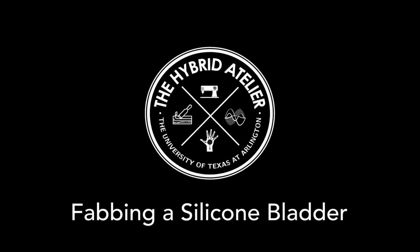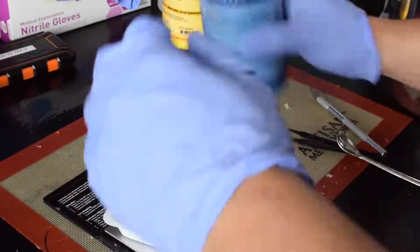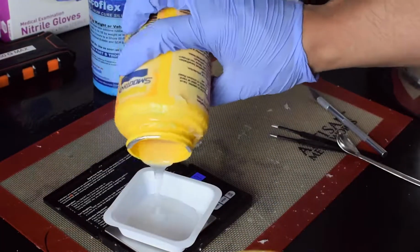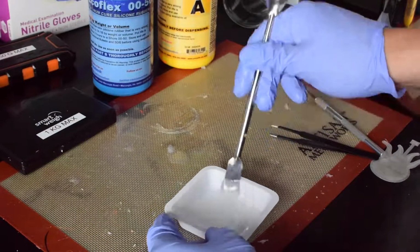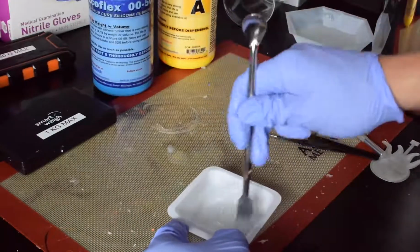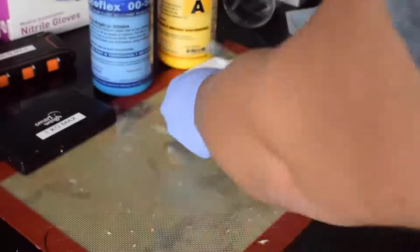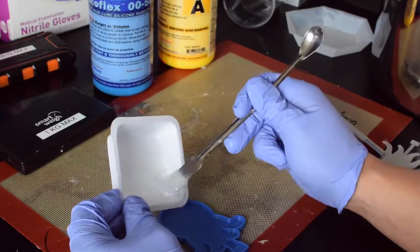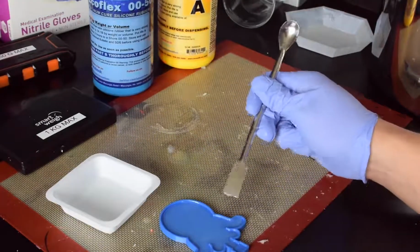So once we have our design files, we're ready to 3D print our mold and separator. We're then going to pour part A and part B of the silicone system, in this case EcoFlex 0050. I'm then going to use a metal spatula to carefully mix and incorporate the two reagents. I'm then going to position my mold in front of me and carefully pour the silicone mixture into the mold, trying to get into every nook and cranny up to the parting level.